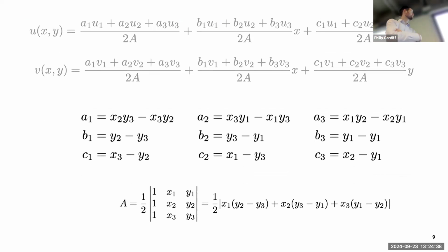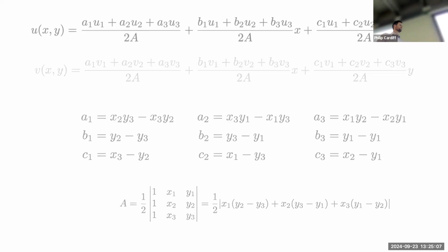And this is what the A's, B's, and C's are. So they're just functions of the coordinates of the nodes. So for example, like Y3 minus Y1, it's kind of like a height of the triangle in a particular direction. So these are all kind of measurements of the height or width of the triangle in some way. So if you picked a very simple triangle that lines up by one, you'll see a lot of these reduce down to just heights and widths. So they're known geometric quantities.